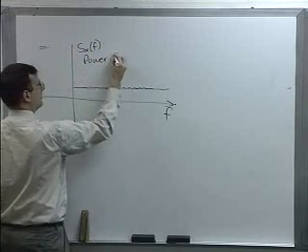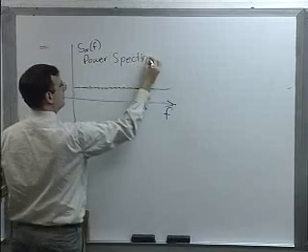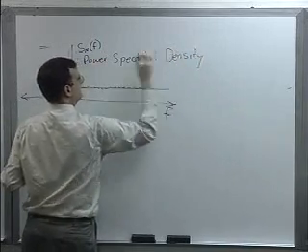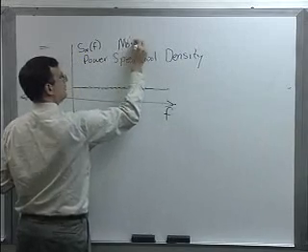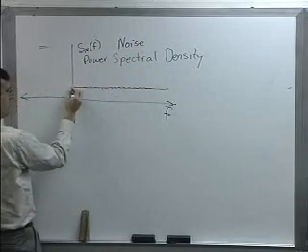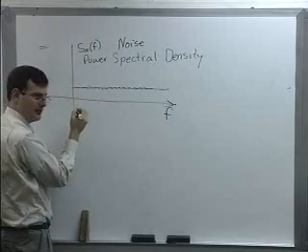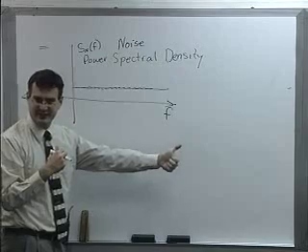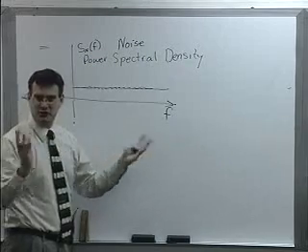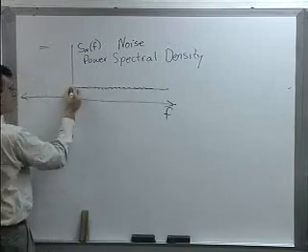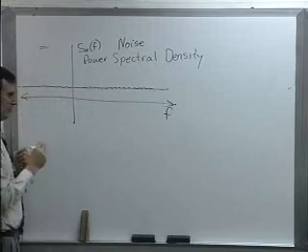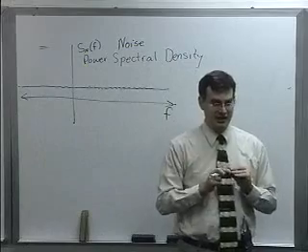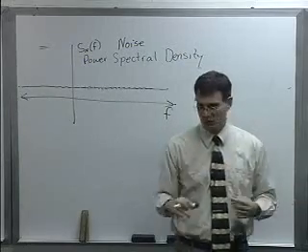Power spectral density for our noise signal. And of course, you never see this on the spectrum analyzer, because spectrum analyzers do only real signals. And real signals always have symmetrical power spectral densities. But of course, mathematically, there's this other part over here in the negative frequency domain to get all the math worked out the way we defined power spectral densities and Fourier transforms.